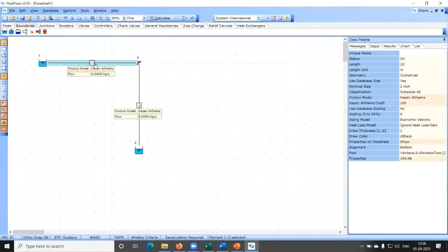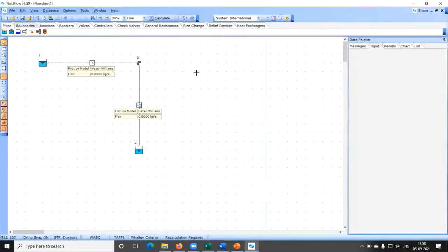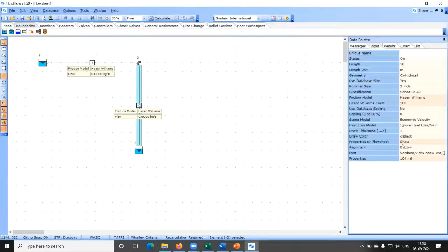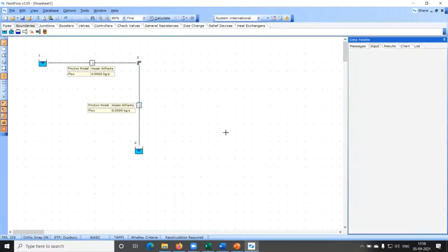Now if you see this first table, it looks all good. It is not overlapping with the pipe, but the second one, this table is getting overlapped with the vertical pipe. So I'll click somewhere else and you can click on the pipe, and in the input alignment, instead of bottom, I'll select left. This way we can move it to left, right, top or bottom position. Once you have completed till this, please write done. If you need help, please ask.